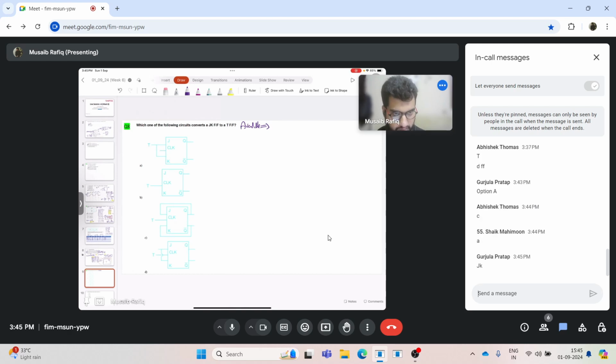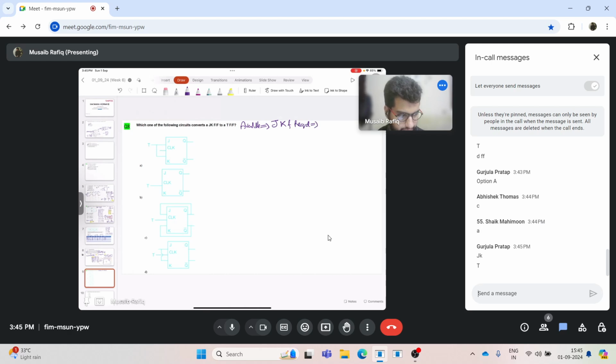It's JK, and your required T. Thank you very much. Now I have to write the characteristic equation of the required flip-flop. So that is J K and Qn.